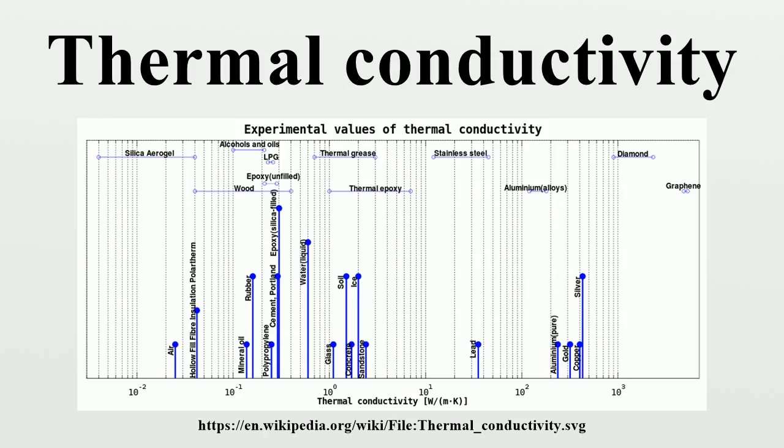Dense gases such as xenon and dichlorodifluoromethane have low thermal conductivity. An exception, sulfur hexafluoride, a dense gas, has a relatively high thermal conductivity due to its high heat capacity. Argon, a gas denser than air, is often used in insulated glazing to improve its insulation characteristics.